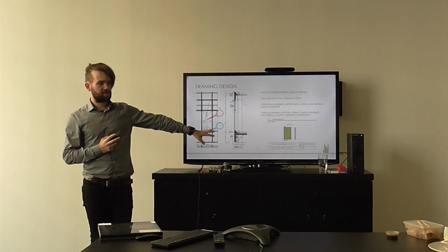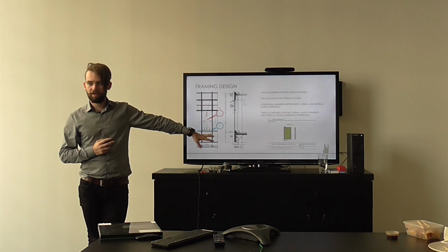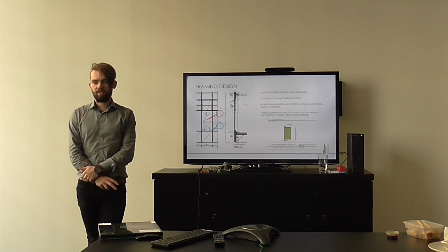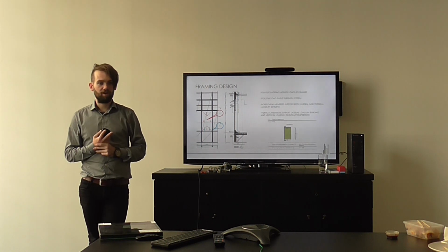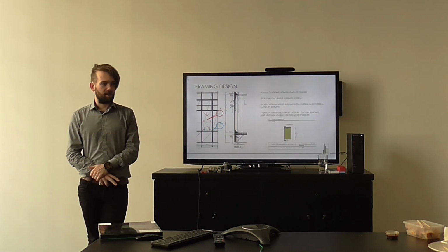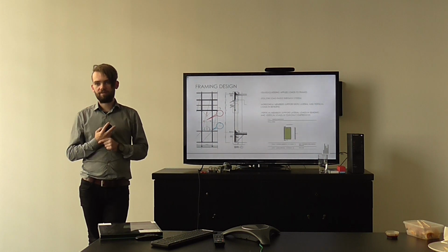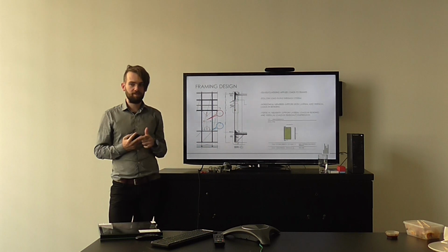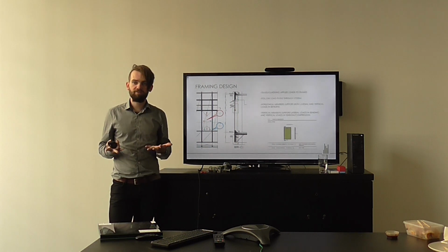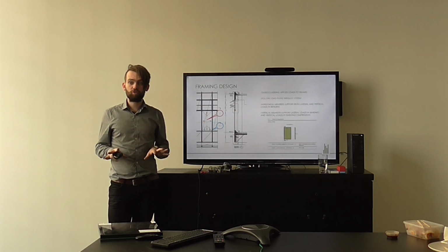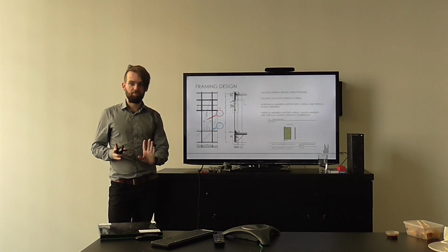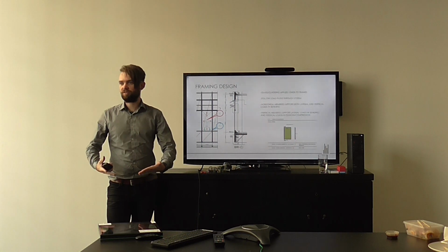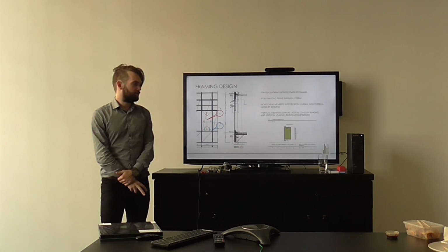So there are some limitations there. You'll find them in every one of our schedules, but typically we try to get this under 20 to 25 mil at an absolute maximum, and then they're usually governed by the actual length of the member. And for transoms or lateral members carrying the weight of glass, the deflection is much stricter than for inward bending. So it's just so that we don't accidentally dead load the glass below or move things so that they'll shatter.